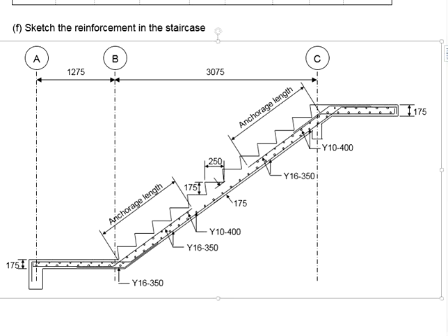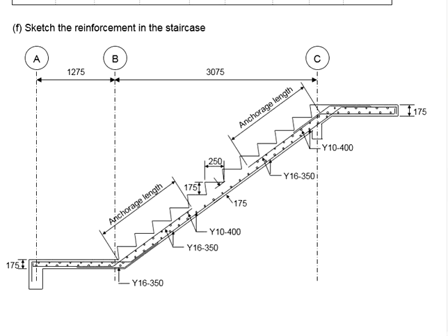However, if you are feeling lacking confidence, it is no harm for you to provide the anchorage length as a safety measure, consuming a little bit more reinforcement in the staircase. Such a design is still okay. Personally, in industrial practice, even though the requirement of the anchorage may end here, I will still provide more as a safety precaution.